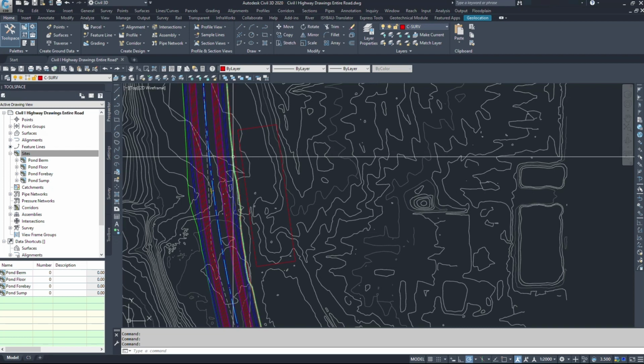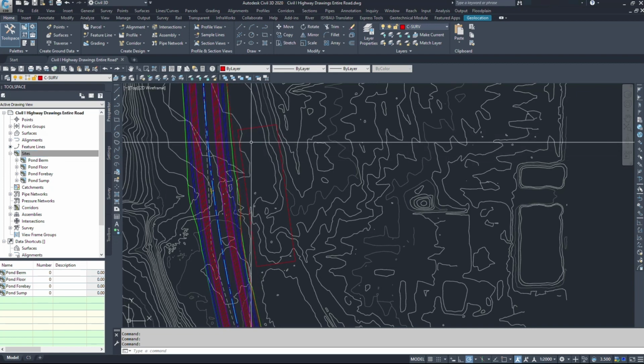If we were to do a pond inlet or a ditch outlet, we'd have to have another site for the outlet of the ditch. If we were to do a ditch, we'd have to have another site for the ditch itself. So we have 2 additional sites. Inlet into the pond, we'd have to have 3 sites. And then an inlet from the forebay into the pond, that'd be 4 additional sites, which is 4 additional grading objects, which gives you more things to possibly corrupt your drawing if proper procedures are not followed. So we're going to stick with these 4 to make things easier.